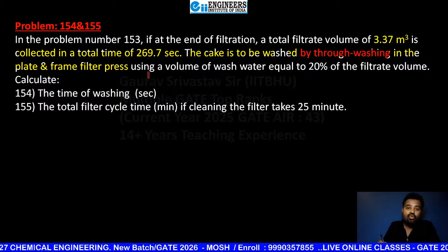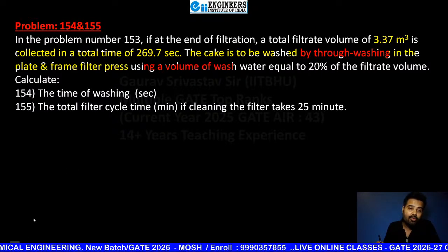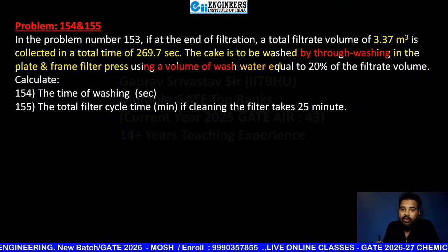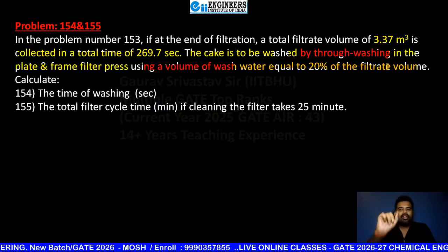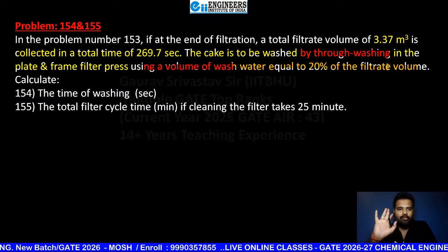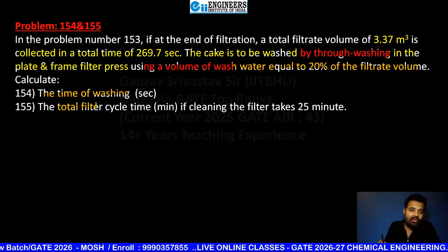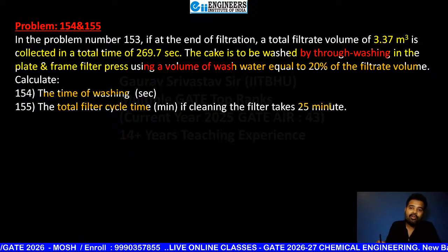And now they are giving the wash water amount, equal to 20% of filtrate volume. That means wash water used is 20% of 3.37 meter cube. Calculate the time of washing and the total filter cycle time if cleaning the filter takes 25 minutes.